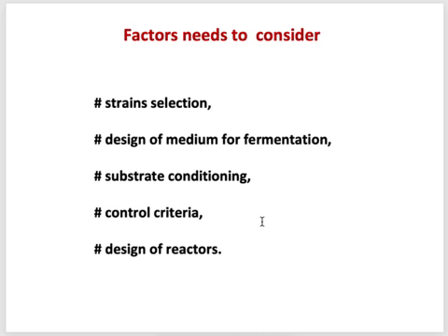So if you want to do SSF, you need to consider some factors, like which strain you will use, the design of the medium for the fermenter, and the condition of the substrate. In this case, the substrate itself acts as a source of carbon, nitrogen, etc. So you need to decide in which condition your substrate will be.